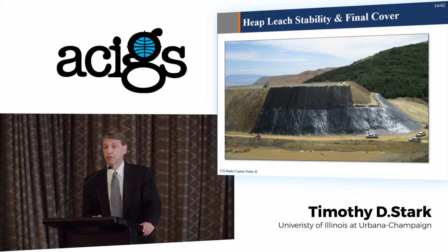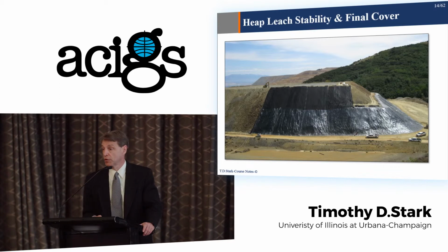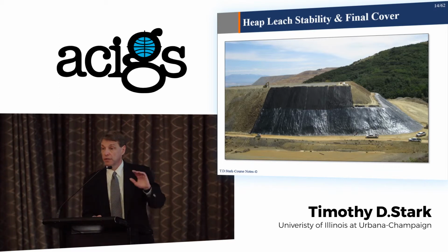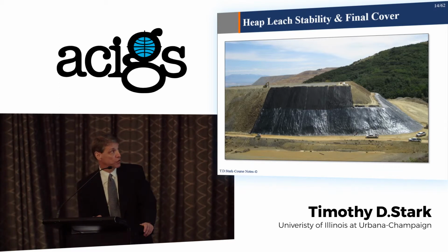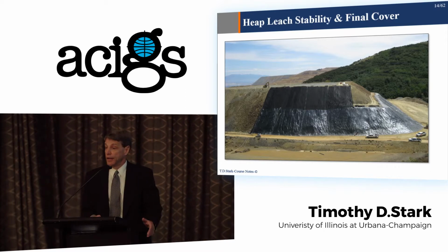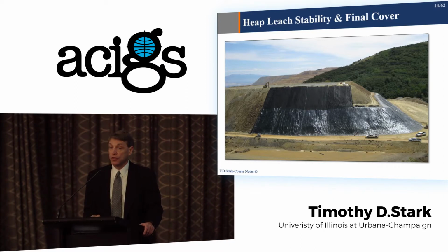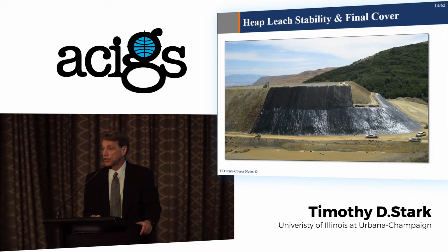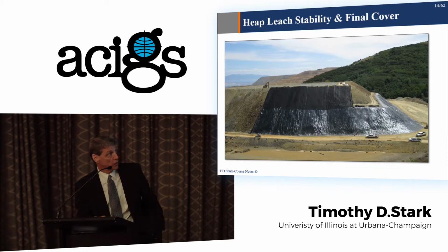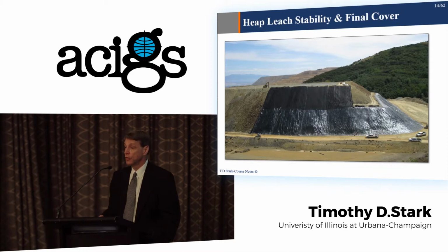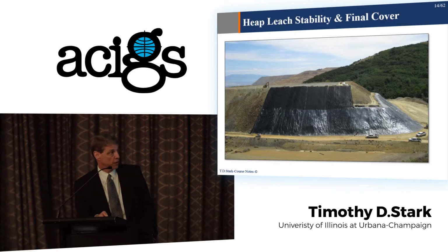So in this particular case, the geomembrane was left exposed, not covered, because the slopes are too steep. And if that's going to be the case, of course the geomembrane should be able to withstand exposed conditions. So some geomembranes are better for unexposed versus exposed conditions. So this will be a long-term exposure, so you need a UV-resistant geomembrane for this application.